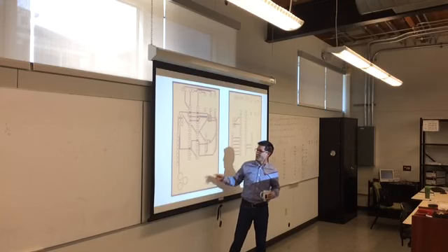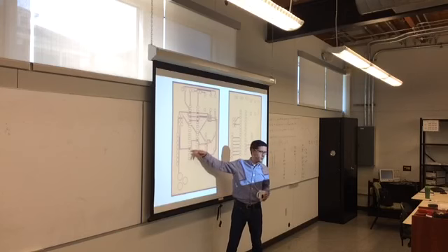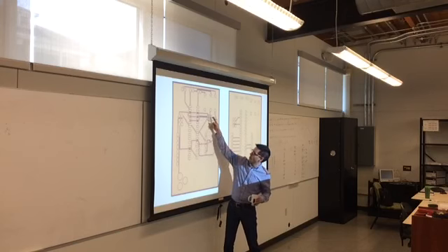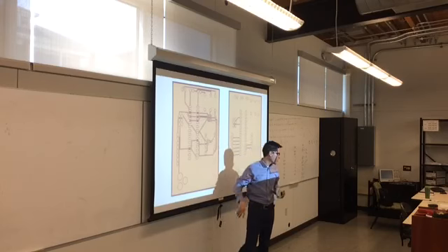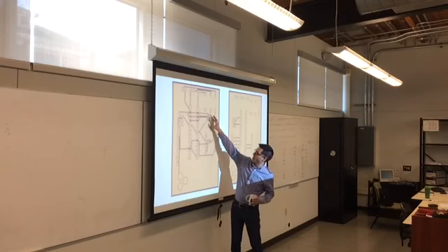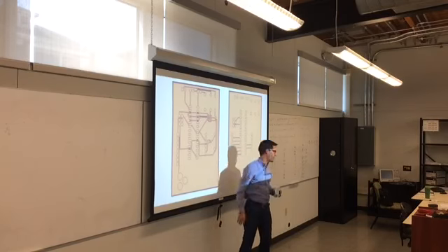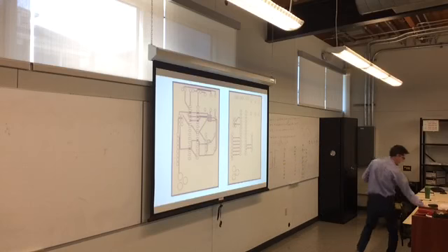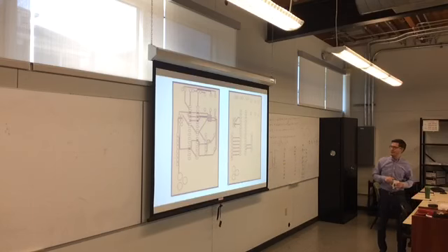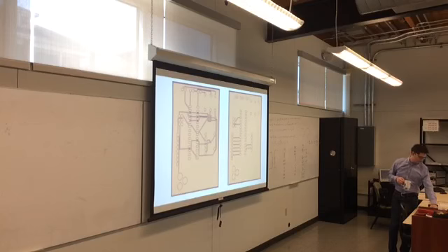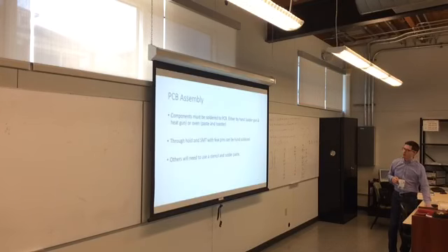This is okay. It's really not good that they've got the routing here between the pins. This routing must have been clearly done by the auto router because this pin is going underneath the entire chip directly over here. It would have been better to take this chip, rotate it, put it nearby. This is not really a space efficient design, but I think the student didn't really care.